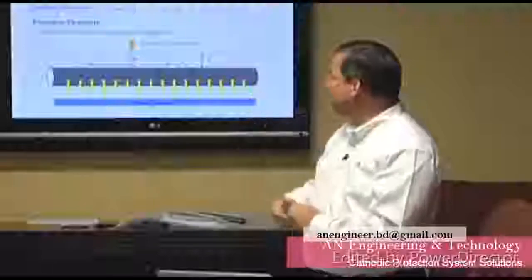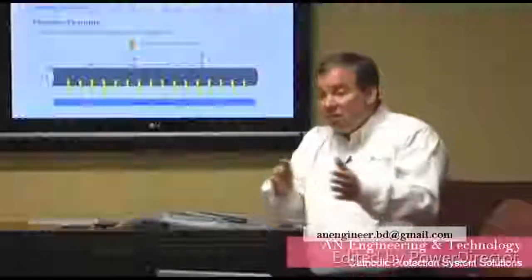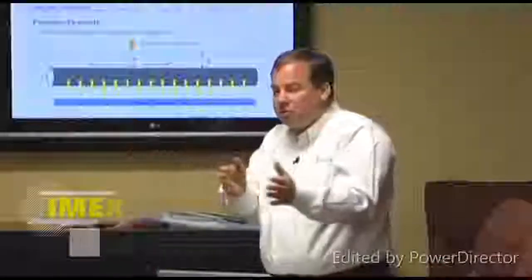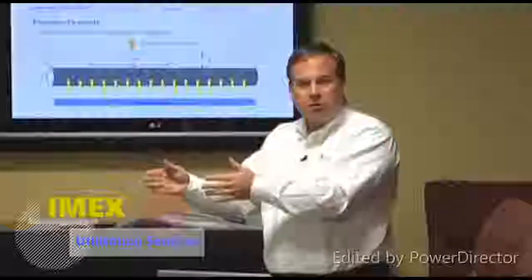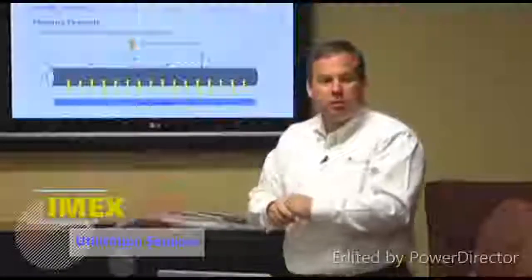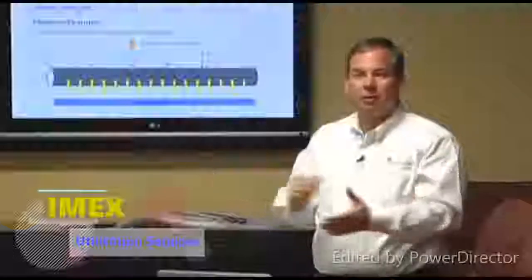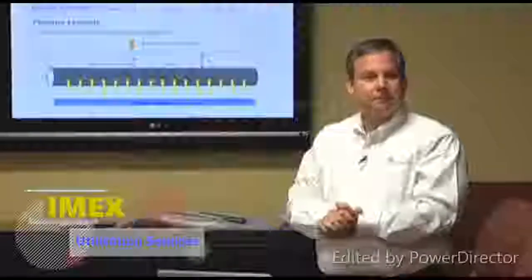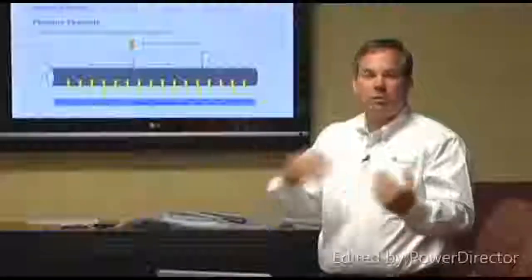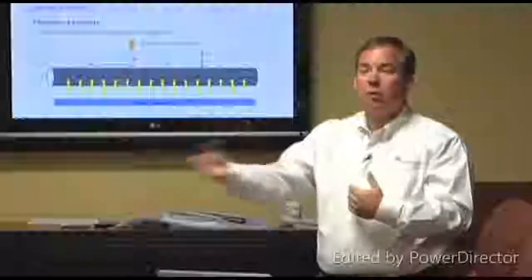So you now see this pipeline has gone from being minus 550 to minus 560, minus 580, with all these little micro differences in potential. I'm showering the whole thing with so much current that now all of a sudden the whole thing is at minus 1,000. And there's no way current's going to discharge off that pipe because it's got current flowing onto it.